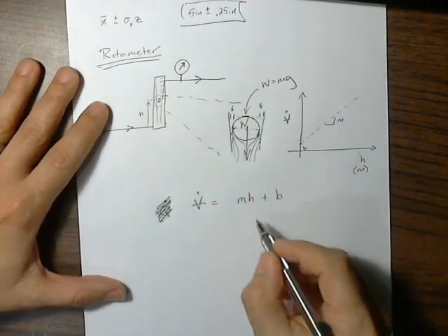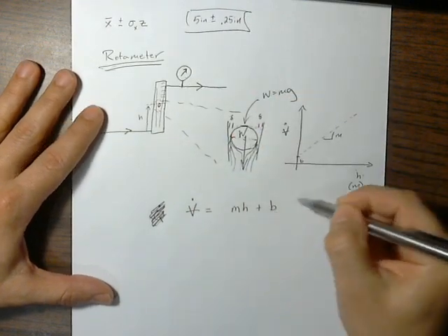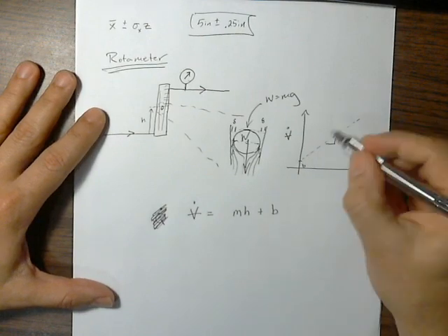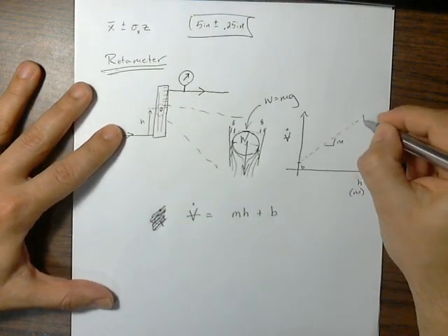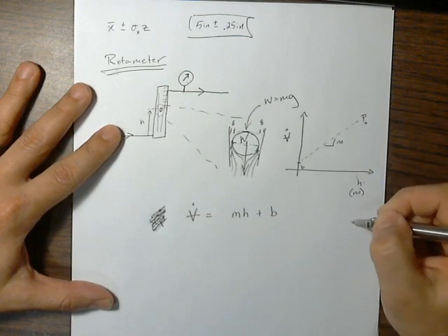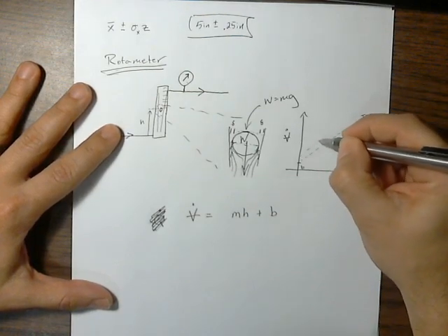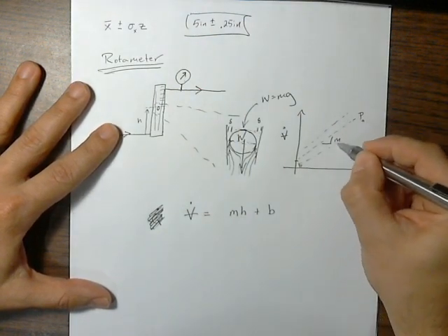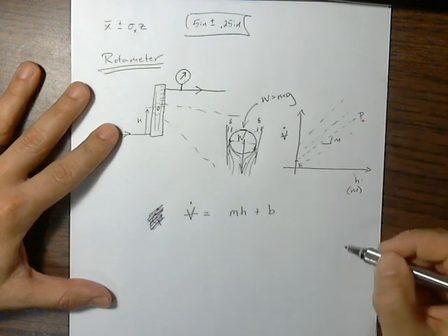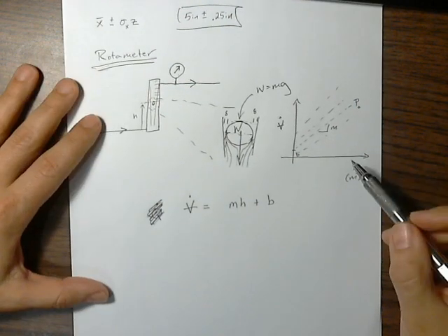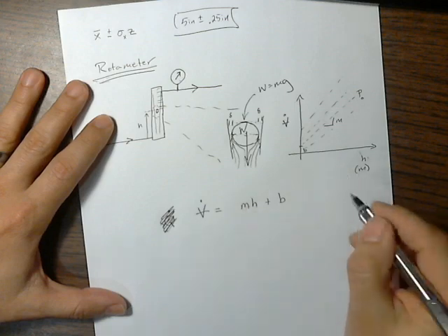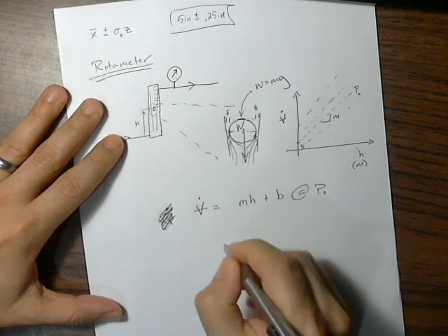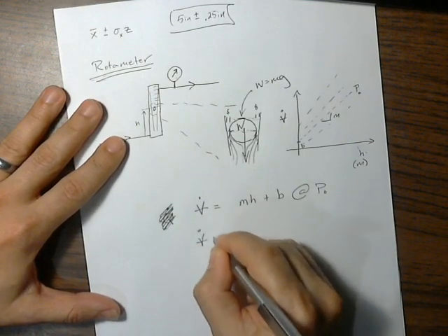Well, as it turns out, it's more complicated than that, because this calibration would be taken only at one pressure. What we find is the whole curve, as I change, so that might be at some initial pressure I'm going to call P naught. What we find is if we repeat this with the gas line at a different pressure, the whole curve shifts up and down with different pressures. Oh dear. Well, but this is something we can deal with. We have math. We know how to do math, so we can deal with this.